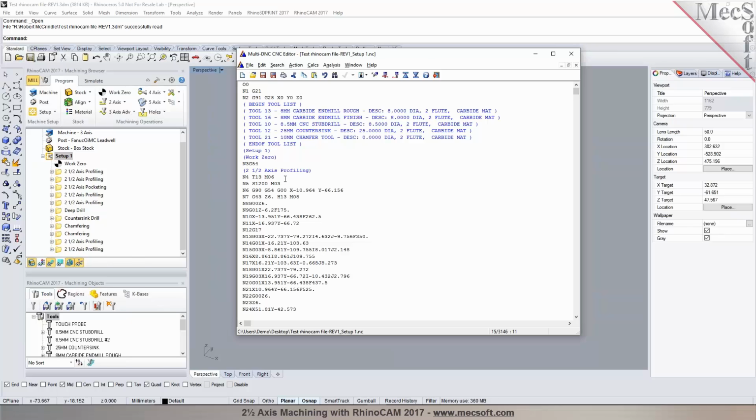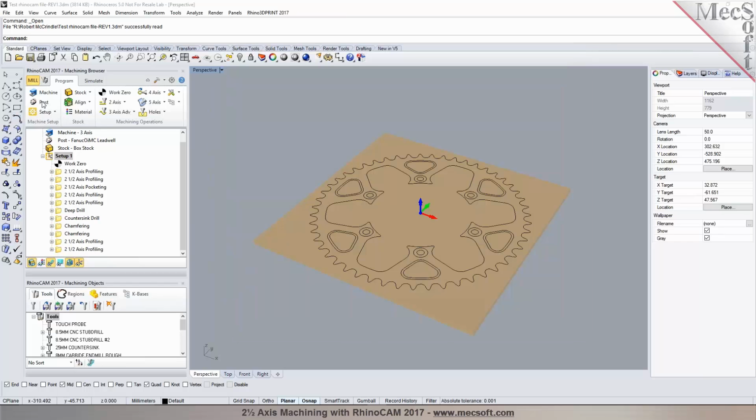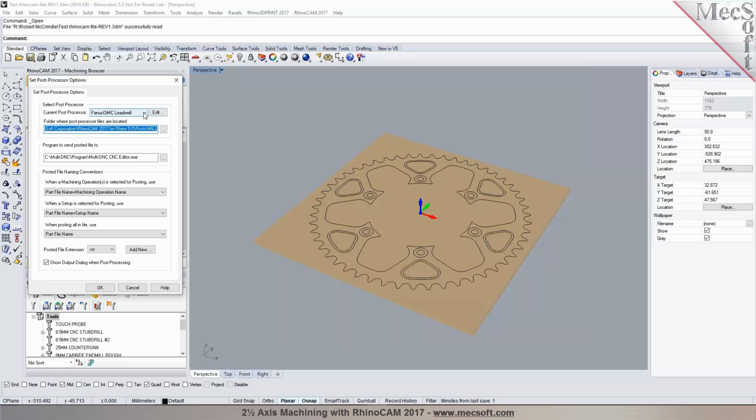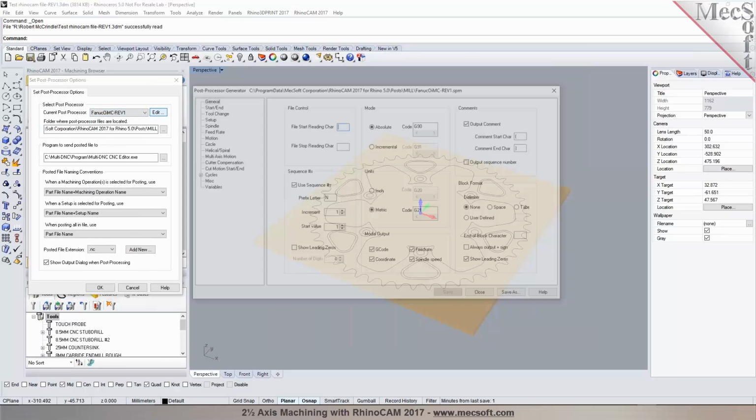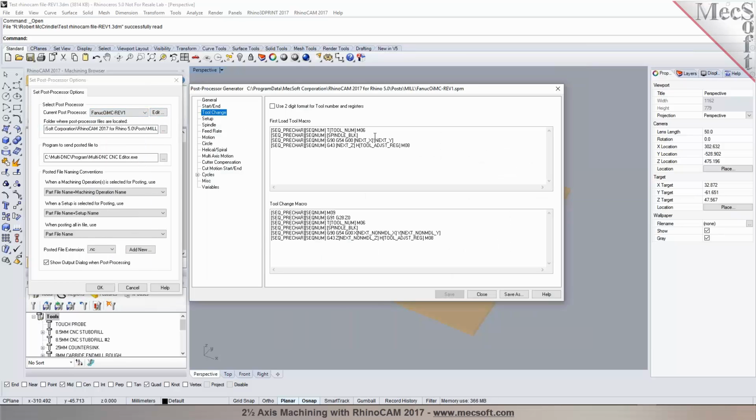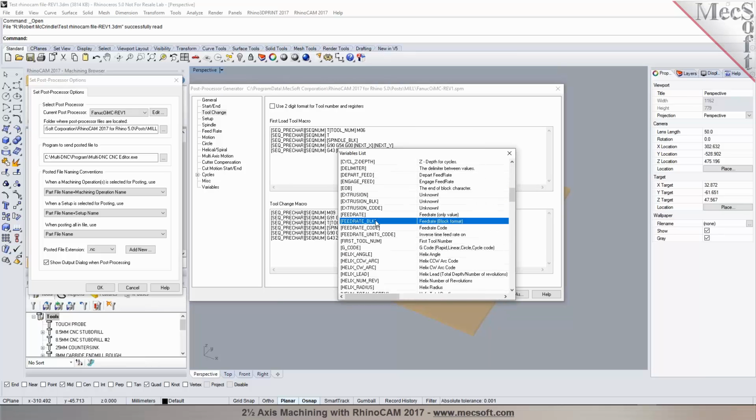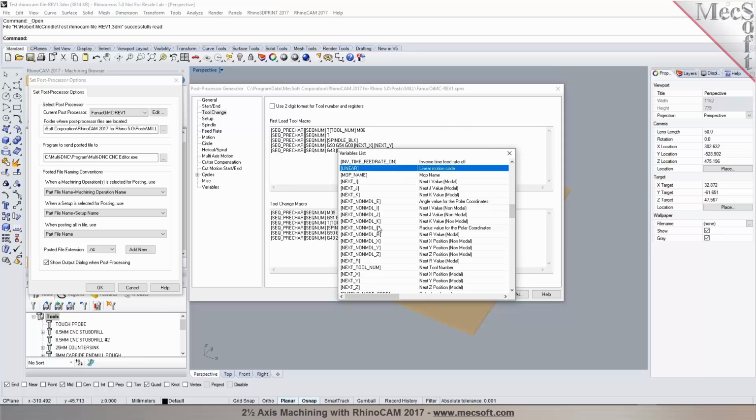Is it possible to set the post processor up so that it prepares the next tool that it's going to use under that line of code there? Absolutely. So here's what we're going to do. Go ahead and use this modified post, and I'm going to use a variable to output the next tool number. So we should have a variable called next tool num.